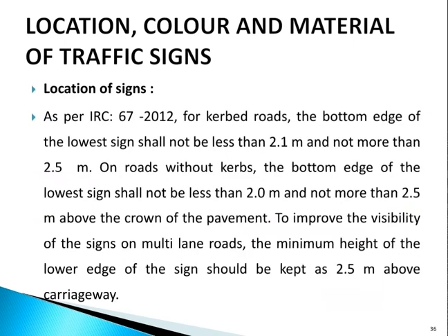And as per IRC 67/2012, for curbed roads, the bottom edge of the lowest sign shall not be less than 2.1 meter and not more than 2.5 meter.